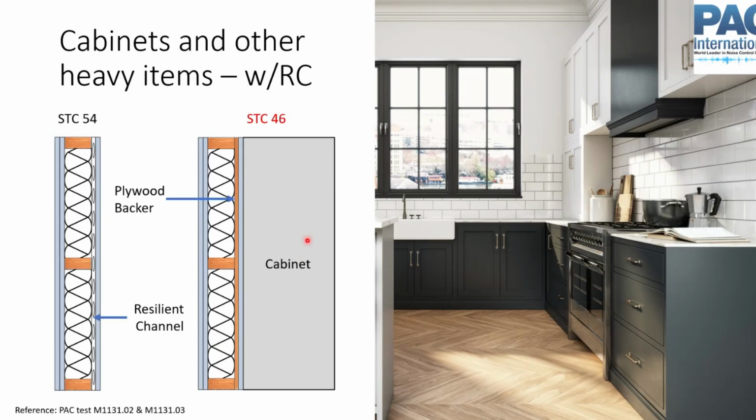If you mount a cabinet on it, which is typical, the way I typically saw this done when I was a consultant is the contractor will put 1/2-inch OSB or plywood backing between the studs and the drywall. Because if you just attach the cabinet to the drywall, through the drywall and into the studs, when you've got this resilient channel there, when they tighten the cabinet in, it'll start crushing that drywall and it'll create issues, cracks, all these kinds of things, right? It'll hamper your installation. So they put this spacer essentially back here, and it also just gives you a wider target.